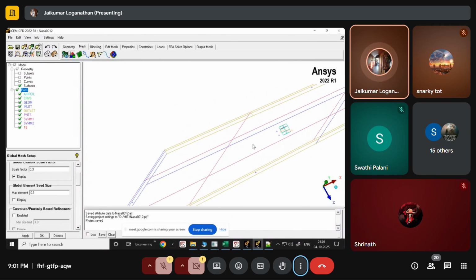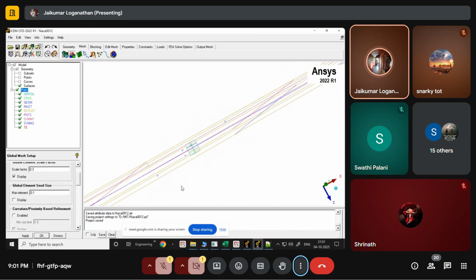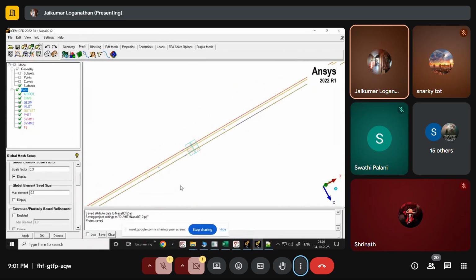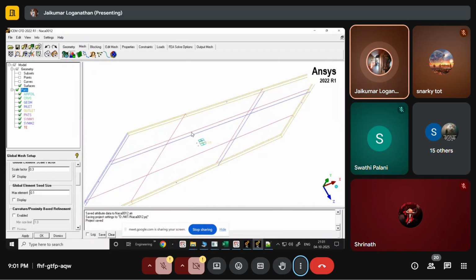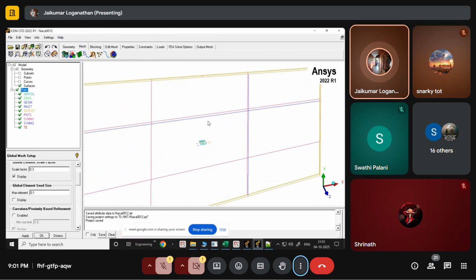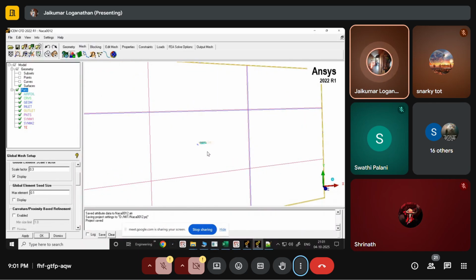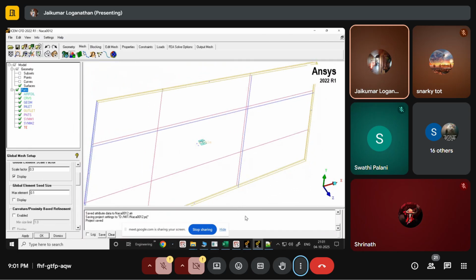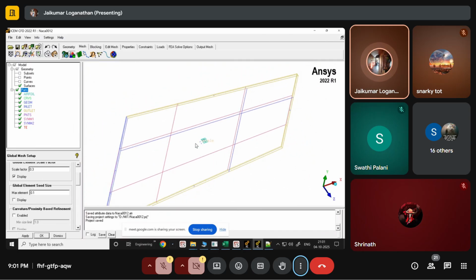So you can see that part of the airfoil is sticking out, right? But another important step in ICEM is to specify what is called a material point or the volume point. Because this is a top-down method, it will mesh everything, and then it will discard the volumes of mesh that we don't need. For example, it will also try to mesh the inside of the airfoil, but we don't need the mesh inside the airfoil. So to indicate to ICEM where to mesh, we create something called the material point.